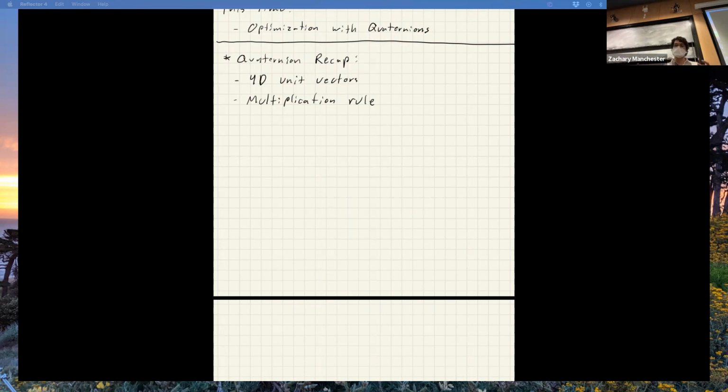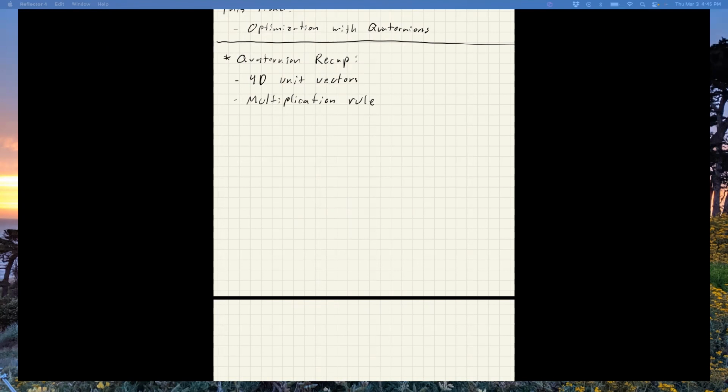What we're going to do here is what we call quaternion kinematics, which is the mapping from standard angular velocity, omega, the kind of thing you measure with a gyro, into a q dot, the quaternion derivative. Generally you don't want to write your dynamics, your accelerations, in terms of quaternions. It's unnecessary: it's got an extra variable in there that is constrained in weird ways, and it's not convenient. Does that make sense? Yeah, that makes sense. Cool. We're going to talk a little more about this today, and hopefully it starts to click.